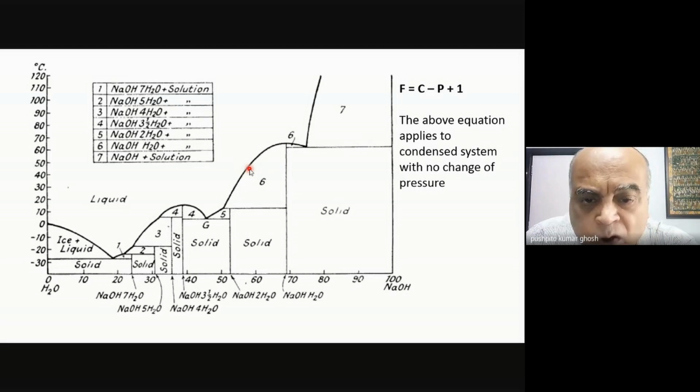And what will happen if I try to evaporate more? I'll just get NaOH, H2O. Doesn't matter how much I try to evaporate and remove water, it's not going to happen. What will come out is NaOH, H2O. So I have to know that, if I want to get into this part, obviously then I have to make sure that I am at a temperature of around at least 90 to 100 degrees centigrade. And then I have to look at the thermal stability issues, etc. And then if I touch this, I would have touched the part of the phase diagram which will enable me to make a pure caustic lye, which is free of water. So please remember, I just wanted to illustrate with a phase diagram that all of these and where all these phase diagrams, etc., become relevant. Are all of you familiar with the phase diagram or the equation?